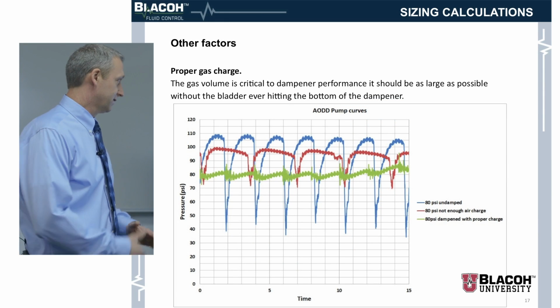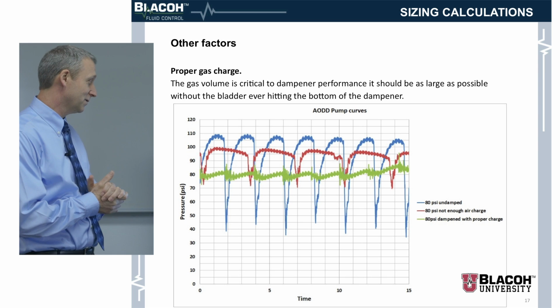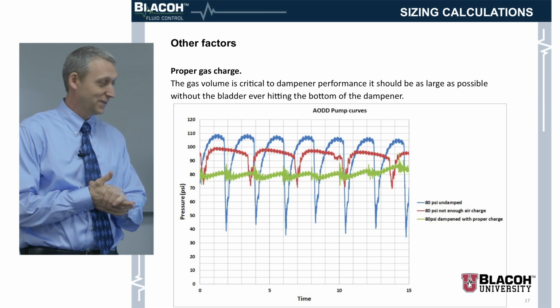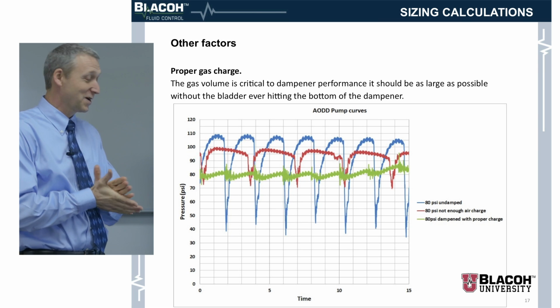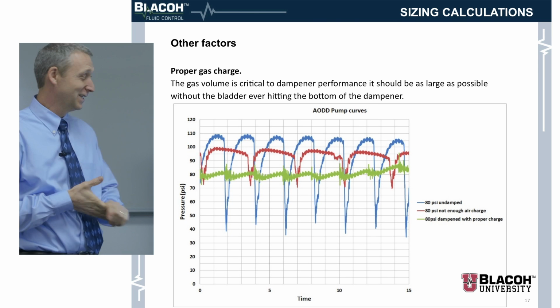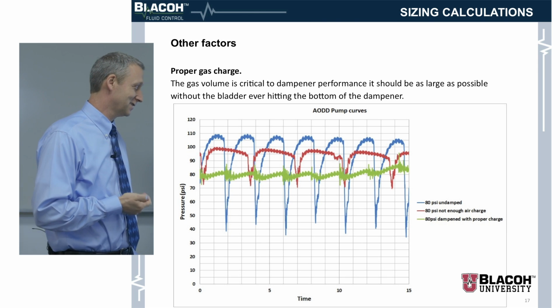All right, other factors. Proper gas charge. We always say this. You'll probably see this in any one of our training videos. There are some very important things that often get missed. Gas charge is one of them, and dampener placement is another for sure.